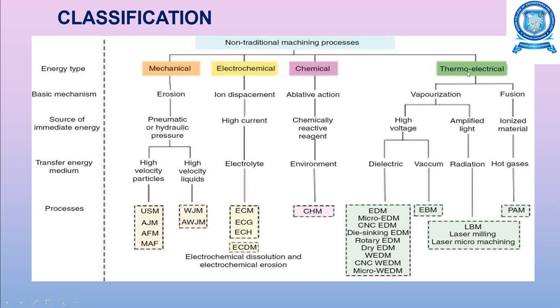For thermoelectrical, under vaporization, for dielectric you have EDM, micro EDM, CNC EDM, die sinking EDM, rotary EDM, dry EDM, and WEDM, CNC WEDM, micro WEDM. For vacuum you have EBM. Similarly under vaporization you have LBM, laser milling, laser micro machining. And for thermoelectrical under fusion you have PAM.